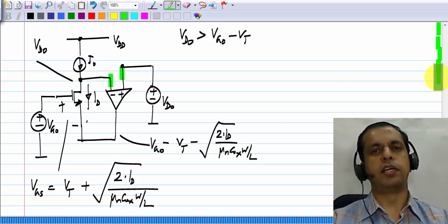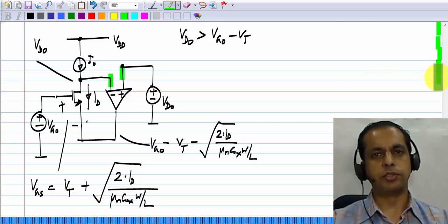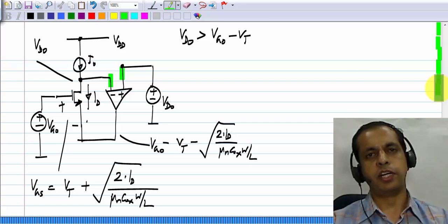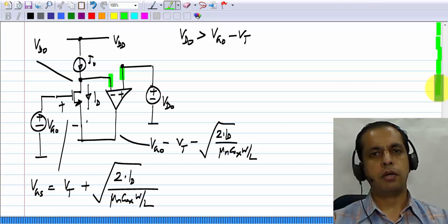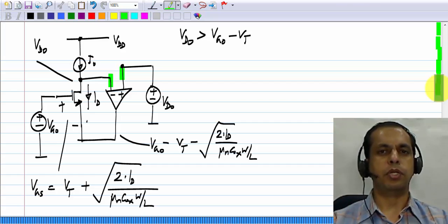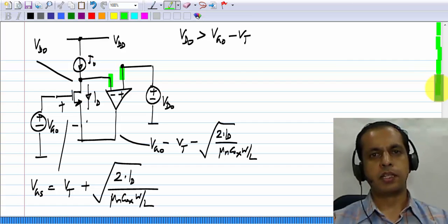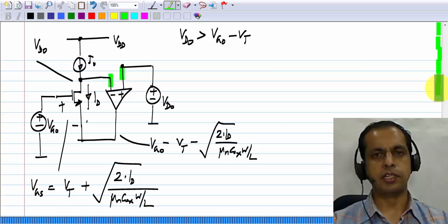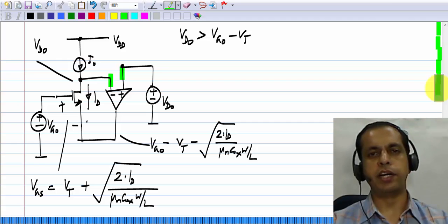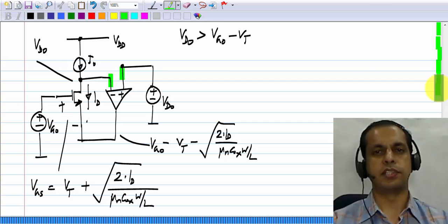If the drain current is more than the desired current, somehow the gate source voltage must reduce, and if the drain current is less than the desired current, the gate source voltage must increase. Okay. So negative feedback ensures that. But of course, negative feedback only tells you in which direction to vary things. The absolute values of voltages are also important to maintain the transistor in saturation region, and you have to pick that appropriately. Okay. The negative feedback loop can be completed by a variety of means. In each case, you have to separately check and make sure that the transistor is in saturation. Okay.